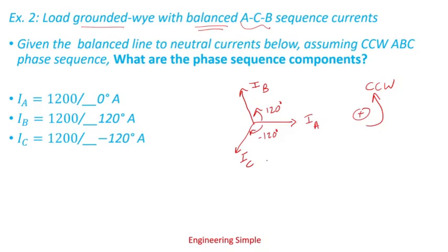So this is negative sequence, if you notice, because if I draw a line and they rotate counterclockwise, A will cross first, then C will follow, then B, so it's ACB. So this is negative sequence and it's balanced. So I should only see negative sequence current. Zero sequence and positive should be zero.